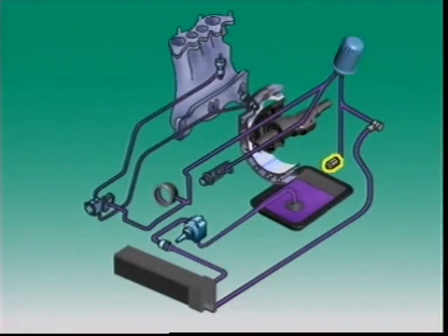A regulator valve controls the oil pressure in the system. The oil goes onto the main bearings and rotor bearings and is sprayed into rotor cavities. Along the way, it absorbs heat, then returns to the oil pan.